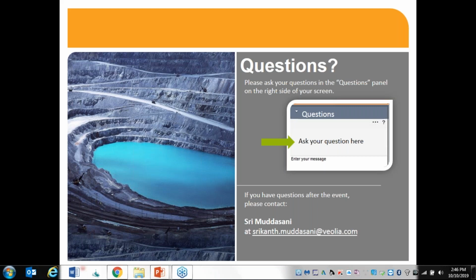Then for the calcium to sulfate ratio, typically I would start around 1.5 to 1 or 2 to 1, and for the aluminum to sulfate ratio, it all depends on your effluent goals. If you're trying to reduce down to 100 milligram per liter or 50 milligram per liter, I would suggest a higher dosage of aluminum to sulfate, around 3 to 1. If you want around 500 milligram per liter of sulfates, do a 2 to 1 or 1.5 to 1 ratio.